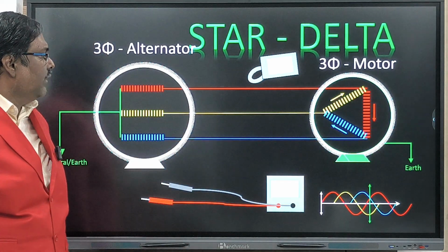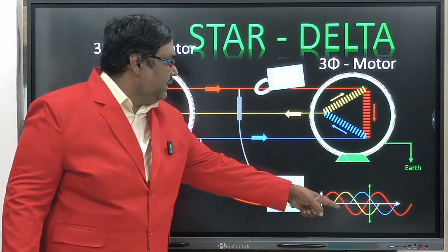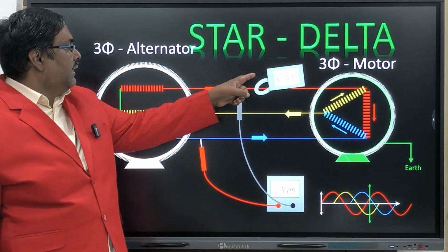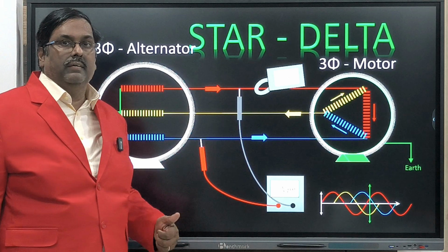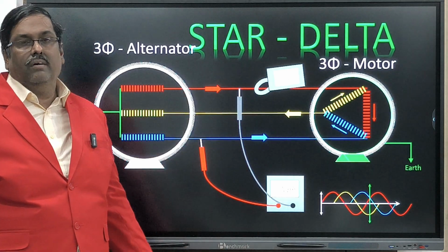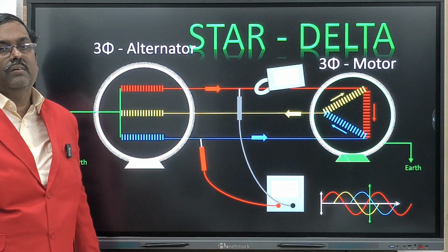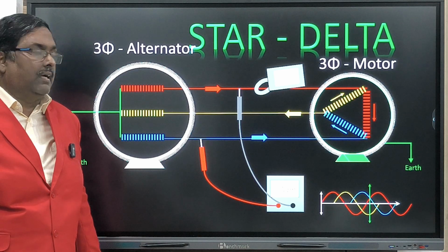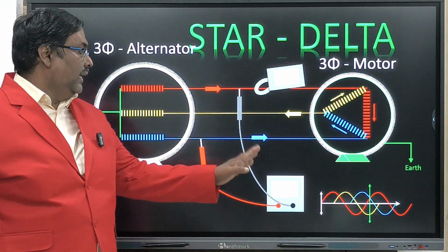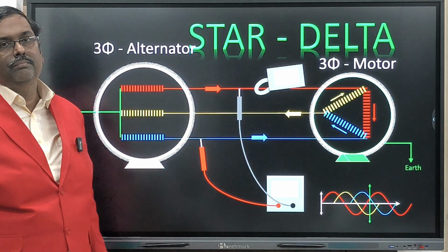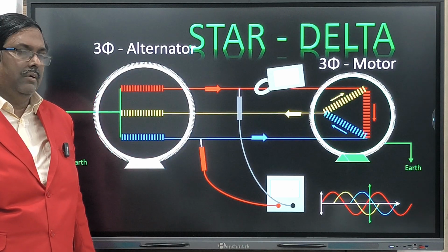Okay. Now I took the same incident and I measured it. You see, current is root 3 more current. Last time I measured the phase current only. Now it is root 3 of I phase, which is 1.732 times the phase current. But voltage is the same. Voltage, no difference. Line voltage and phase voltage are the same. So line voltage is equal to phase voltage now.